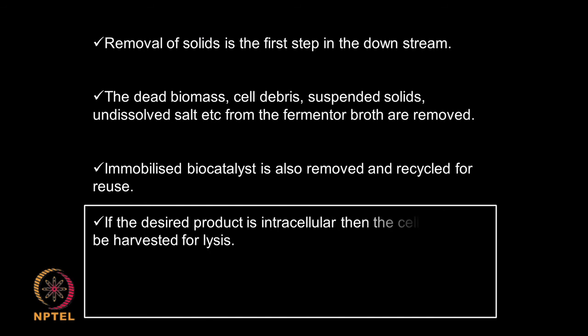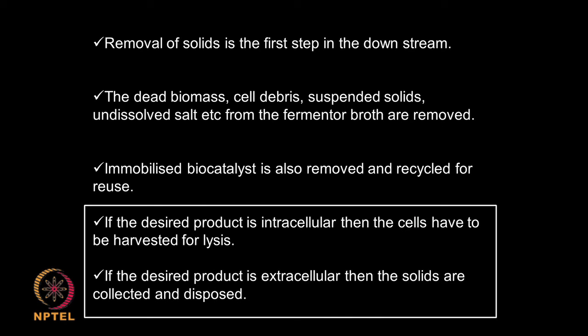There are two different situations when you are looking at a solid liquid separation. If the desired product is intracellular, that means your product is inside the cell, so you have to harvest the cells and lyse the cells to get your product out. If the desired product is extracellular, you are not bothered about the solids. So, you filter the solids and then dispose of the solids, because the liquid is what contains your desired product. You collect the liquid, then you start recovering your product from the liquid, whereas in the other case, if it is intracellular, the desired product is inside the cells.